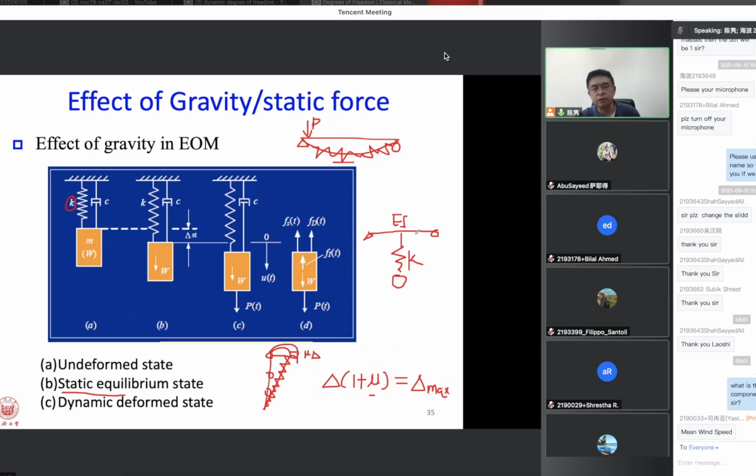Of course, you can still use this, as long as it's a linear one. This is simple. I think it's similar to your homework. You have one spring here which represents this beam, and another spring here which represents this one, so the two springs are connected in series. If we set this one as K1 and this one as K2, it's two springs in series.